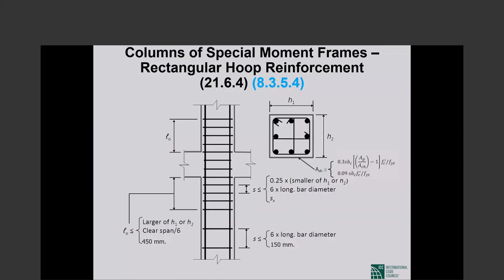It happens to be the same piece of reinforcement. It serves two purposes. When we try to figure out if it is sufficient for one purpose, we use f sub yt of up to 100 ksi. When we try to figure out if it is sufficient for the other purpose, we use f sub yt of 60 ksi. There is no contradiction that I see. Okay.